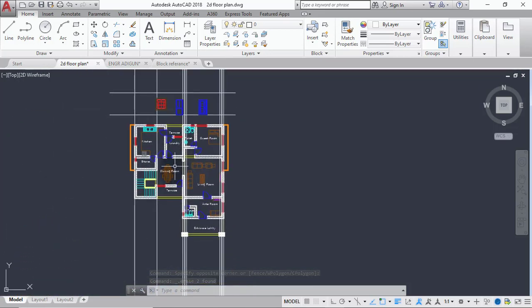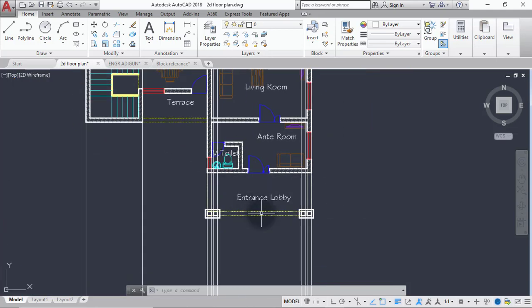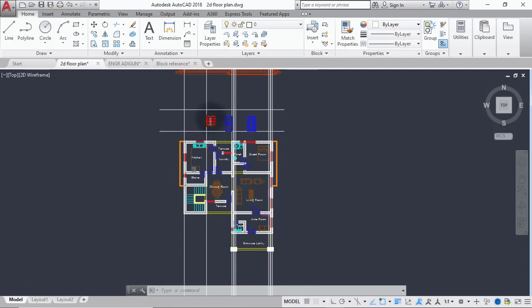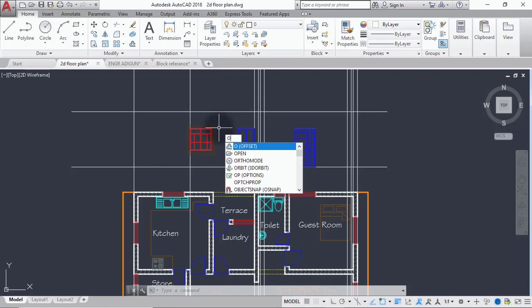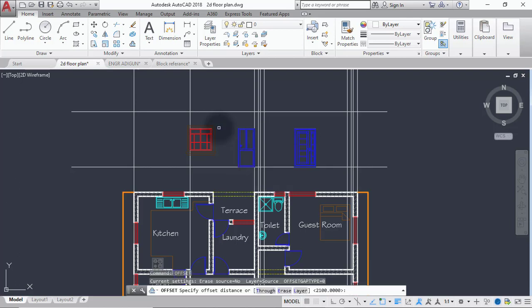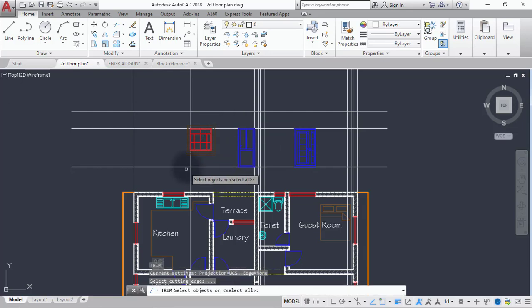What I'll take care of next is our arc here now, or let's say our entrance pin here now, and the same thing we have here now. I'll take care of them, and to do that now, I'll offset down 900 mm. That is the distance from the floor to that point is 2,1. So I'll just offset 900 downward, because if you subtract 2,1 from 3, you have 900. Offset 900. Just bring this down and trim away the unnecessary part of it.